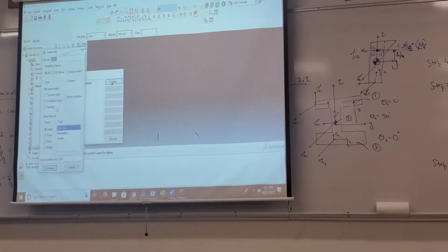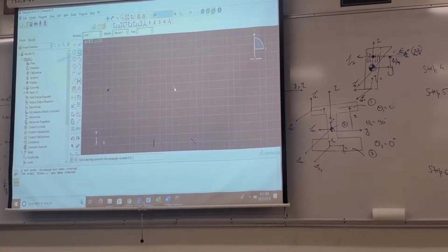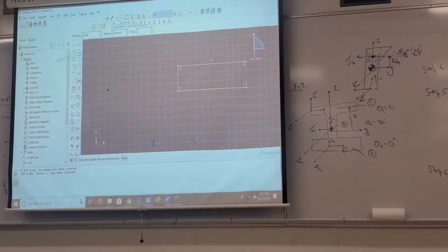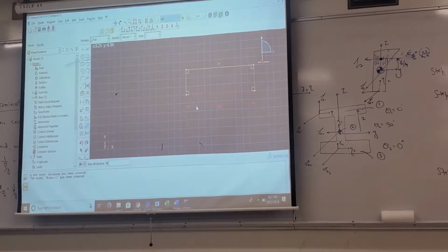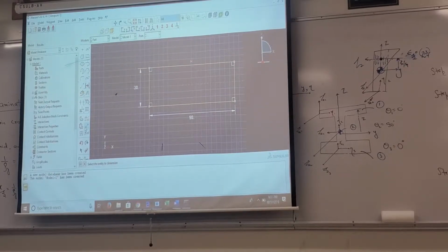Creating a part which is an extrusion. So this means just use a flat plate. We'll put the dimensions here, let's say the same thing as 90 by 30, but 90 millimeters by 30 millimeters in this case. So we have this, it's a bit long, so let me modify that to 15. 15 is better.